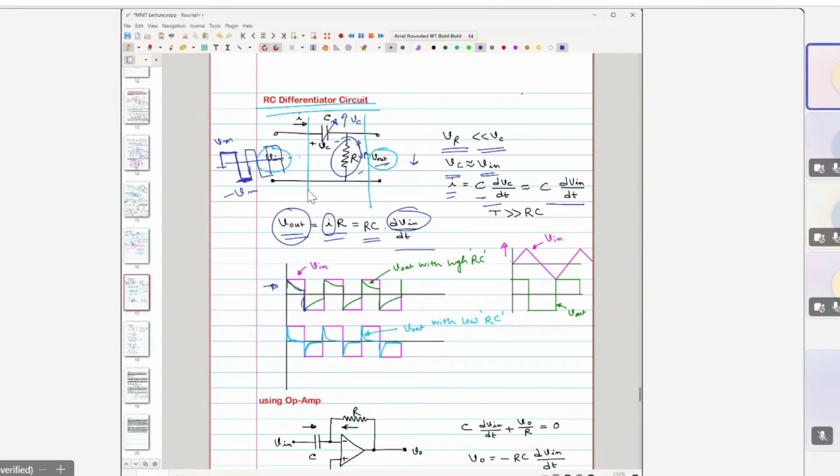But after that, what happens? Now the capacitor is again building up charge, now in reverse polarity. Earlier it was building this side plus, this side minus. Now it will be this side minus, this side plus. Opposite polarity. As a result, the voltage drop across this R will also gradually start falling. You can see the voltage drop gradually starts falling, right? Again the input toggles, and again the same thing happens here.